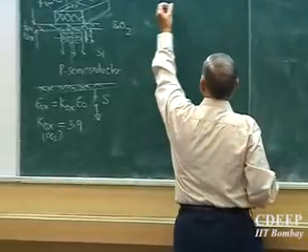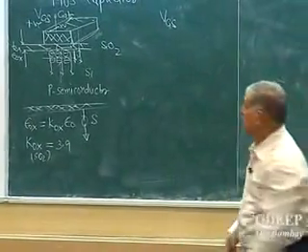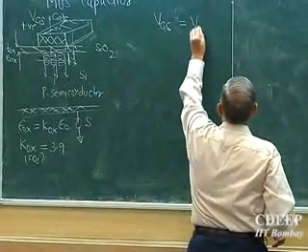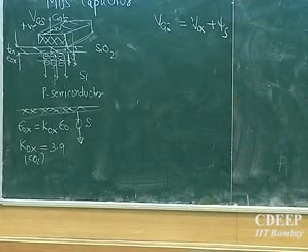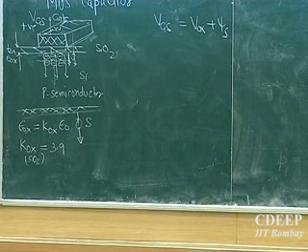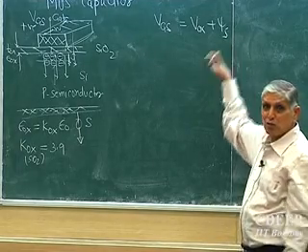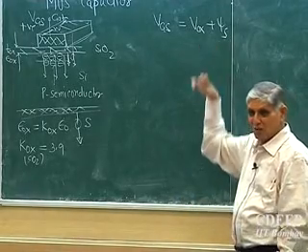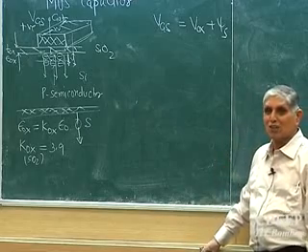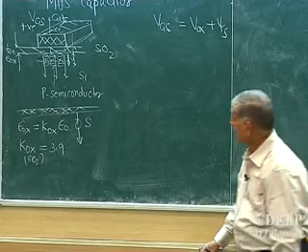So now I say, if I apply VGS, it is divided into oxide voltage plus semiconductor voltage. Is that correct? Semiconductor voltage plus oxide voltage. With this I know everything, because once I know surface potential, I know carriers, I know everything of that. But I don't know what is Vox. So now I start looking into Gauss's law once again. I say, Gauss was such a great man, do help me a bit. So he gave me a good idea.